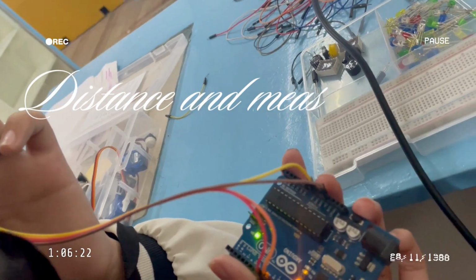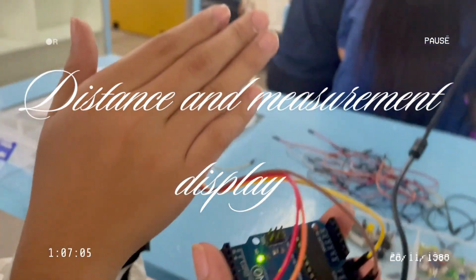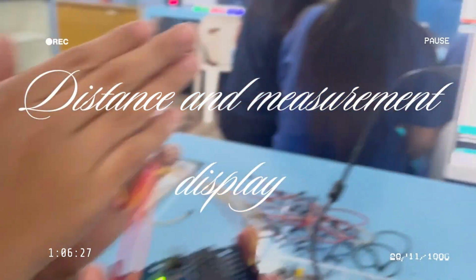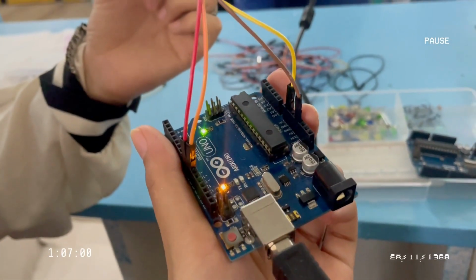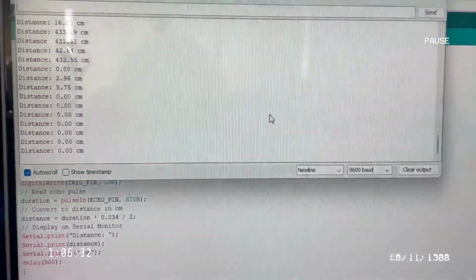Activity 1. Distance Measurement Display, Version 1. In this experiment, we used an ultrasonic sensor to measure distance and display it on the serial monitor. The setup was easy, but we had to carefully connect the trigger and echo pins. This technology is commonly used in distance measurement and object detection systems such as parking sensors.